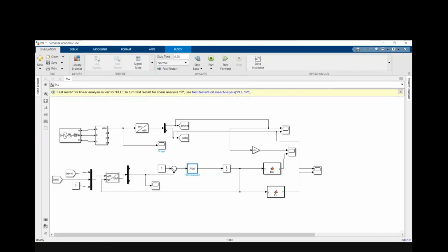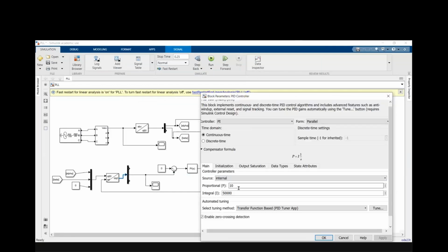As I said, after dq0, these are some constants, but you're taking omega t from them. You can see this derivation in Generalized Theory of Electrical Machines by P.S. Bimbhra. So it is like you are applying a step input to the PI controller and you are observing the system response. It is just only one sine function. It's a simple function only. And you are going to tune that value.